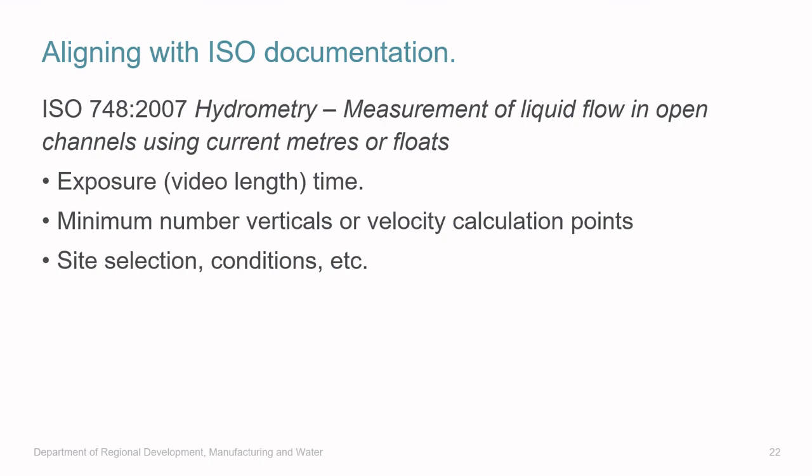The main point when we put the document together was to try and align with existing documentation that was already out there. For example, ISO 748 has a number of recommendations regarding things such as exposure time, the number of verticals used in discharge calculation, as well as information for site selection and conditions.